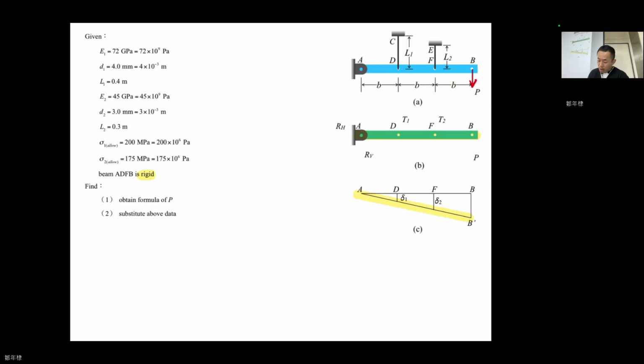Now again, at this A here, we don't know the reaction force, right? The pin will fix the bar, like my fingers fix the bar, which means you cannot go up, and you cannot go left or right. So there must be a vertical reaction and a horizontal reaction. We don't know the direction, so we just assume up and right. And again, P is here.